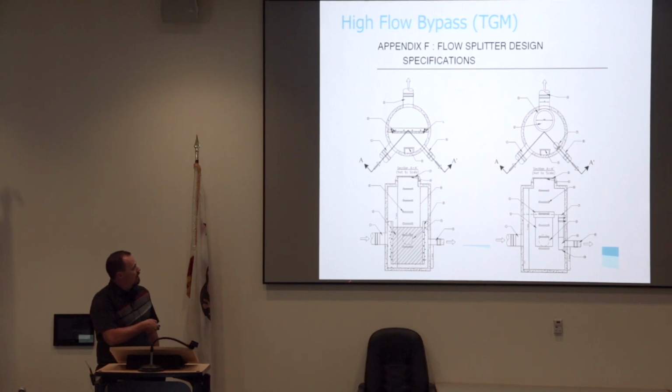The first one is basically a weir wall within a manhole. Say you've got an 18-inch pipe coming in, and a weir wall that's sized per the hydrology calculations for that 0.75 inches of rain, and then you have your low flow pipe going to the BMP itself. Say here it's 8 inches. Once your whole system downstream gets inundated and filled up with that 0.75 inches, the water in this manhole would overflow over the weir and then bypass.